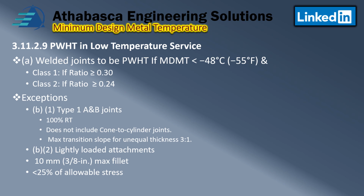And we talked about lightly loaded components. They define that as less than 25% of the allowable stress. One other thing is LP or MPI per Part 7 is required. So there are a lot of exceptions here for post-weld heat treatment in service at low temperatures.